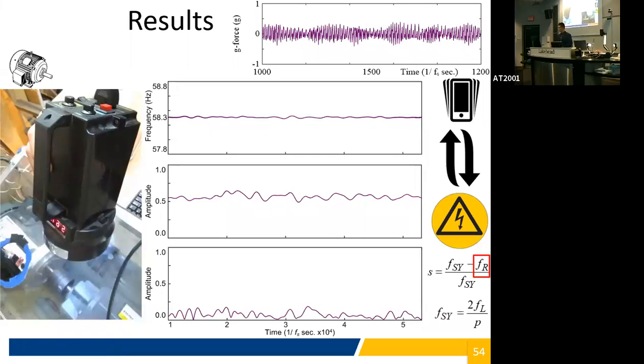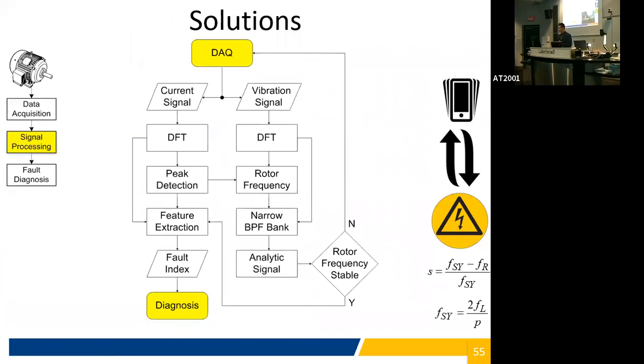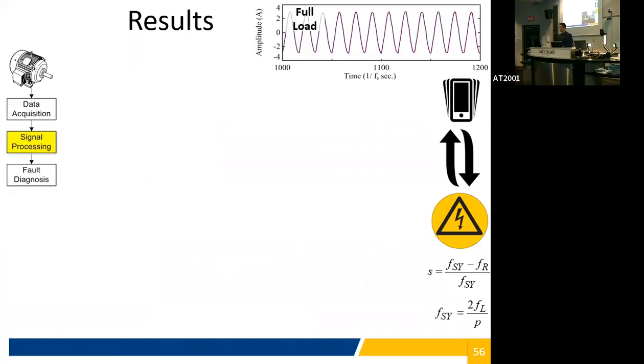And so, of course, this rotor frequency corresponds to slip, and slip is an important quantity which we use to do current-based feature extraction. So let's look into what it looks like when we use the speed to find features related to the fault in induction motors.